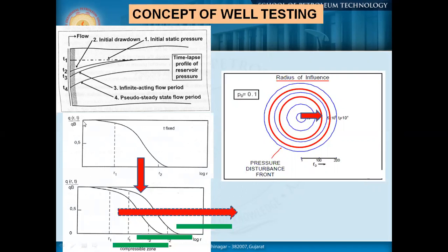1 means this area has completely given the support. That means the Q which we are producing at a well at a specific time has been supplied by that area. If T is fixed in this graph, that means when we are producing at a specific rate or closing it, the area right from this dotted line to this point is only supplying your material.